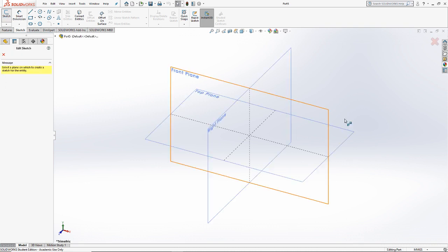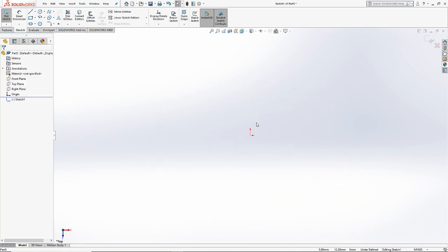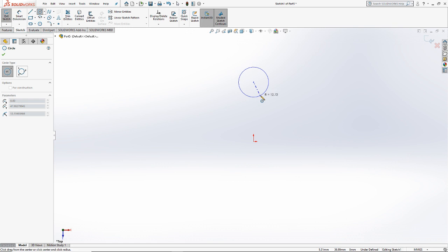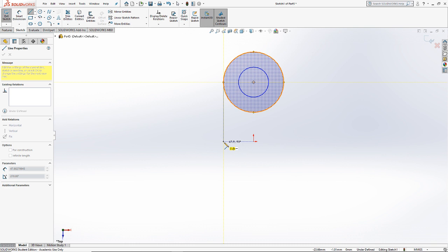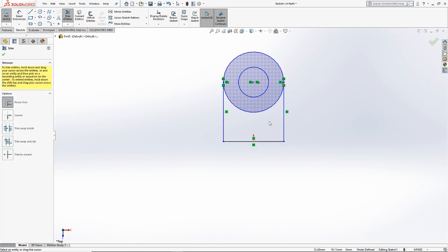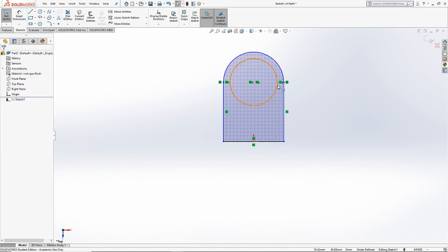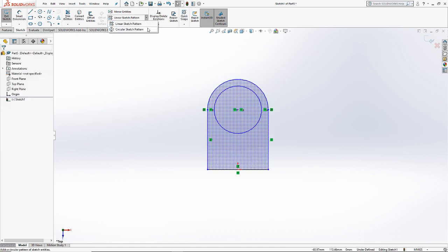let's go in and create a sketch this time, and your pattern consists of the same setup, except this time we are in a sketch and not talking about features. So I've got the same arbitrary shape. I have the ability to create a pattern within the sketch. And the way that SolidWorks handles a pattern of entities within a sketch and a pattern of entities within features is different. Because it can move around your references within the sketch, but it can't do that for 3D geometry.